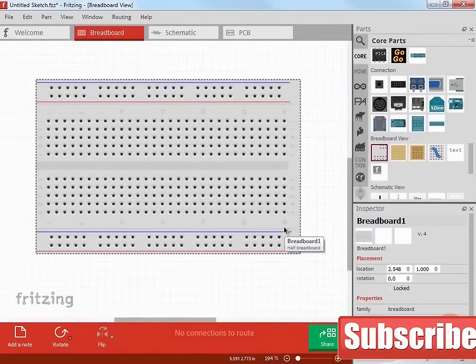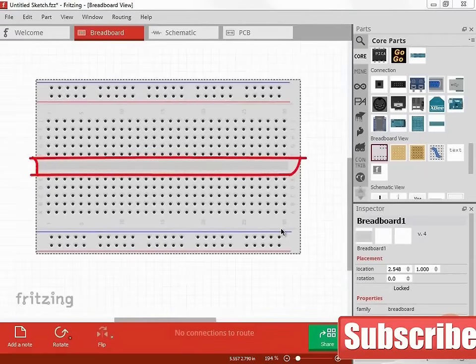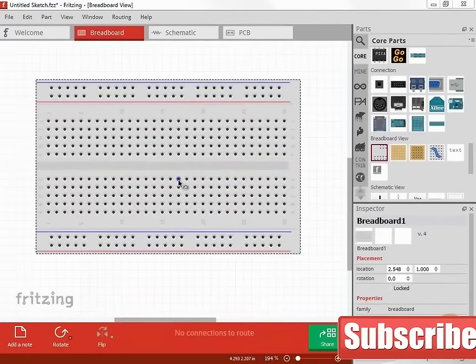It is important to understand how the contact points are connected. The breadboard is separated down the middle with a channel. This is typically where an integrated circuit would straddle, so that all its pins land on isolated columns of contacts. The highlighted pins show areas of common electrical connection. The contacts are arranged in rows and columns.